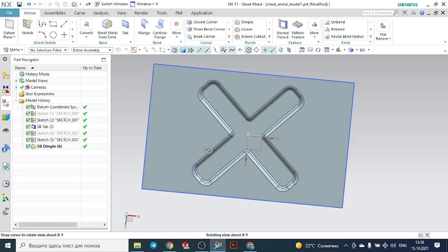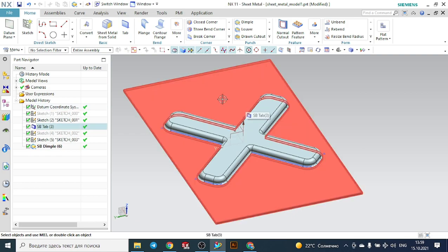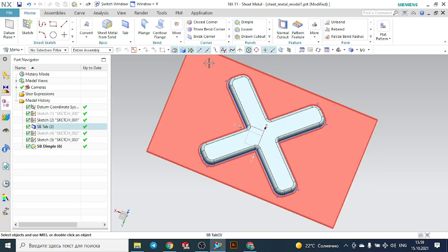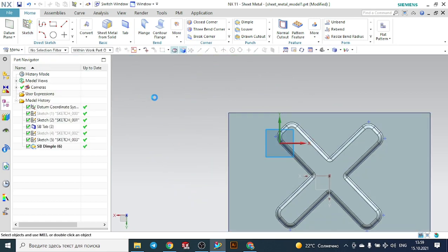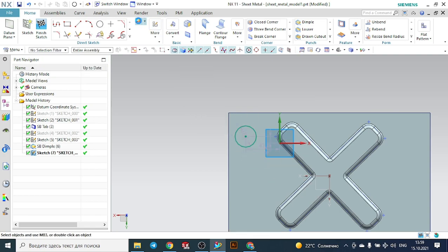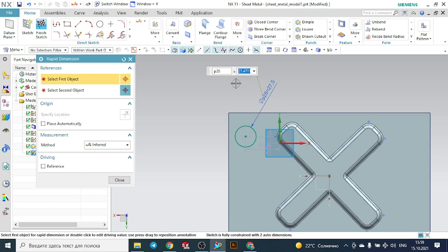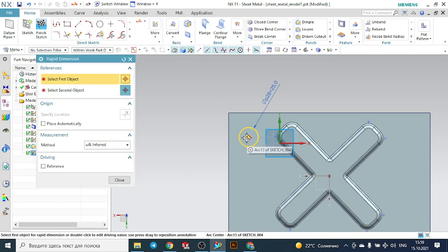Maybe you have seen in car manufacturing such systems with such an option. So it will be obtained by the pressing of this sheet metal, this kind of elements. So it is one option. Also you can create the same system, for example, with a simple sketch. For example, let's draw the circle here. So let's make it 25 and define its position, for example, to be accurate.